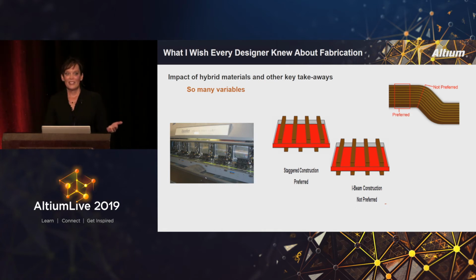That ceramic-filled material has the same kind of issues, right? It has scaling issues, and you put those two together, it can be a very complex design. So what will often happen is a scout lot will be run. They'll take one panel, run it through the entire facility, and then scale the tooling to match how those materials moved and shifted. Which is great. I mean, it definitely improves yield, and it's a good practice, but it does take extra time that needs to be planned into the project, and it is expensive to run that scout lot through.